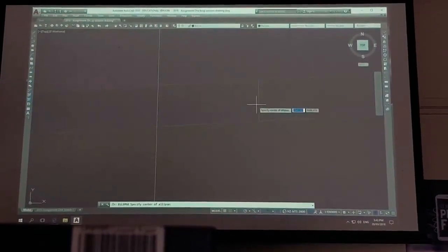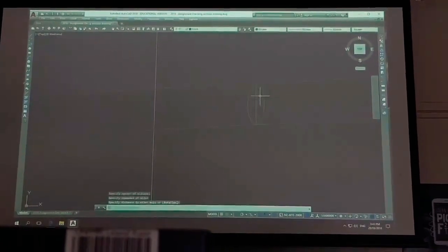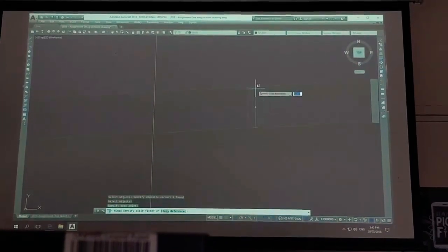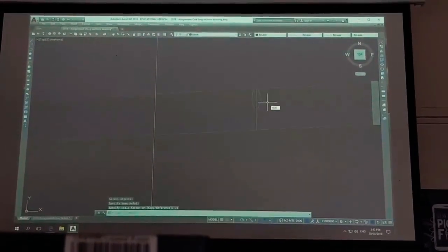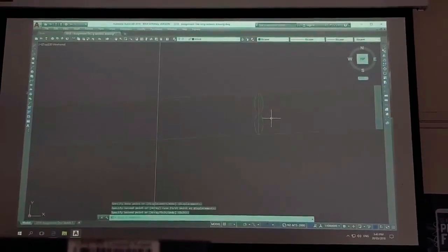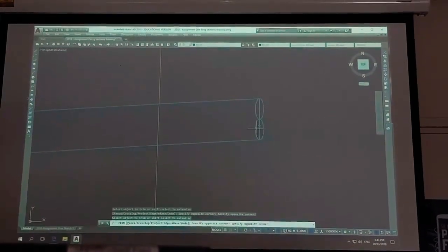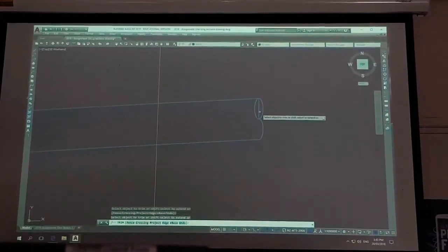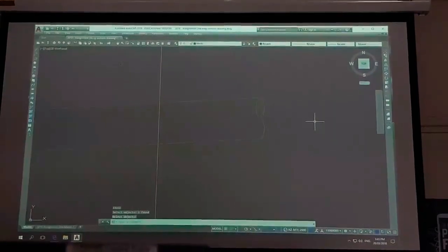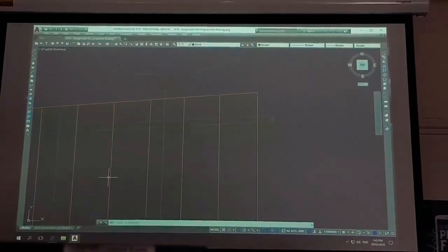centre to centre, so from the centre to there. I'm going to scale that from that point by 0.5, I'm going to copy that from here down to there, and I'm going to trim that off, starting with these two, and then that one, and I'll erase that one. There we are, using the ellipse, I've created a continuous pipe.